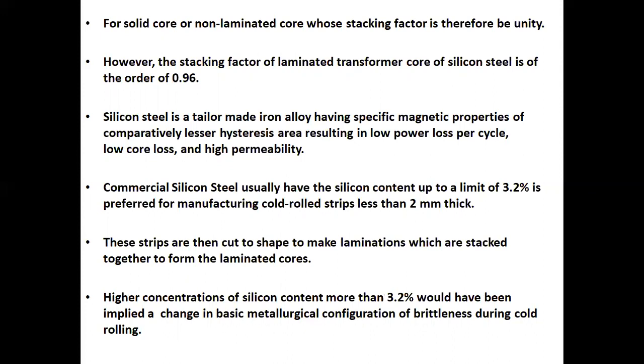Silicon steel is a tailor-made iron alloy having specific magnetic properties of comparatively lesser hysteresis area, resulting in low power loss per cycle, low core loss, and high permeability.